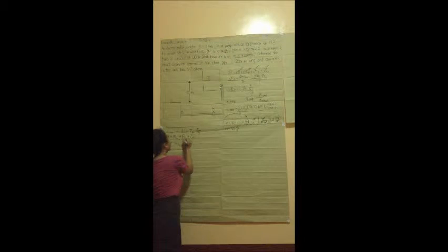Fc has the formula of Kc times velocity squared over 2gc alpha. Alpha is a correction factor for flow, but since we are given water, we assume it to be turbulent. And for turbulent flows, alpha is 1. So this is going to be 1.